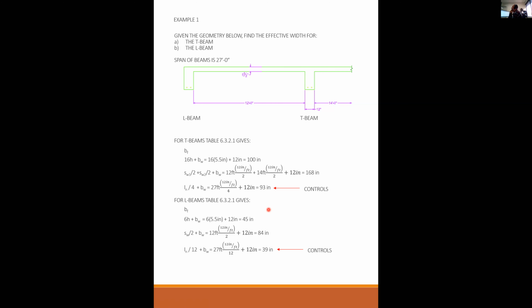No, we don't do that. What we're trying to find, and back to Omer's question as well, is when we design this beam, we can't use all this concrete. We only use the concrete that is in the effective width. So when we go to analyze or design this T-beam, the only concrete that exists for the purposes of our beam is what's in the red rectangles.